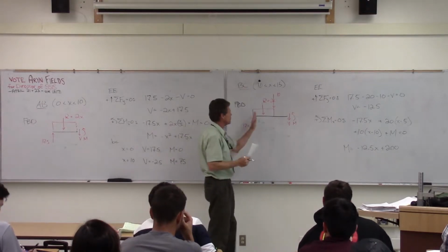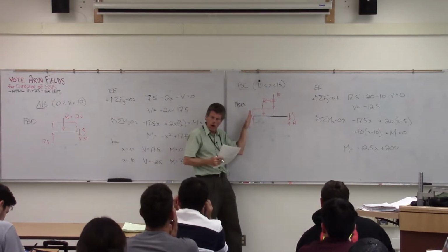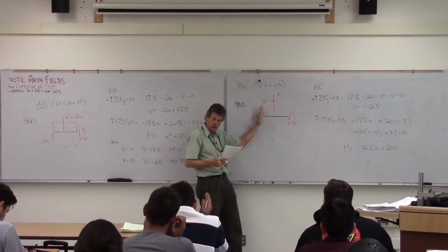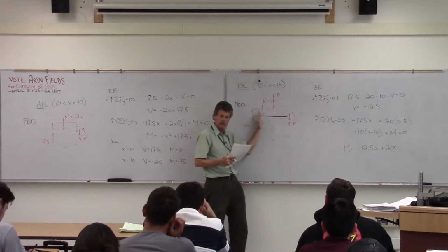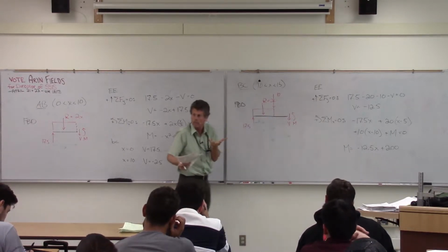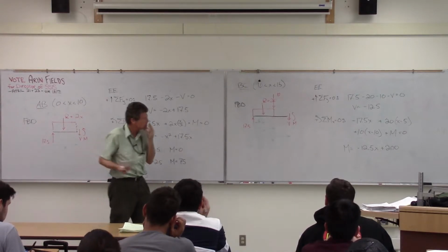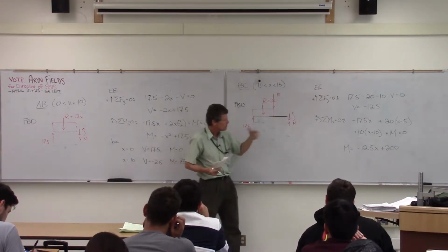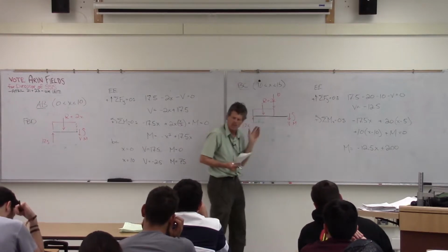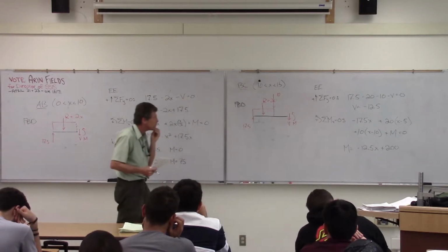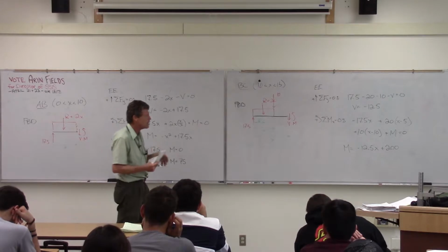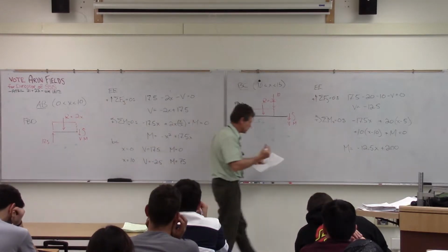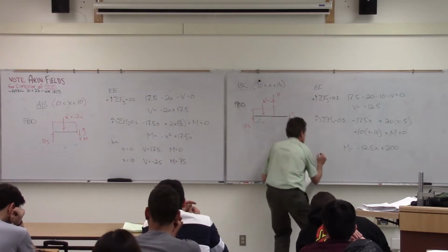Which again makes sense because all of these loads now, even in the equivalent load, are all in fixed locations. The only thing changing is my moment arm. So I should expect to see my moment changing by some sort of a linear value there, with the starting point there too, but that's the y-intercept, and we don't care about that because it's not valid for the equation. And then what we're going to do is look at our boundary conditions again for this.